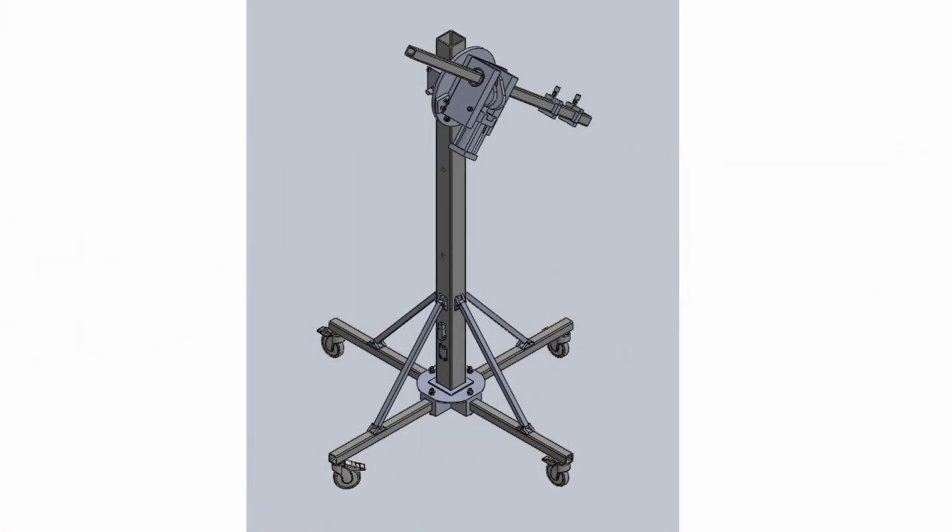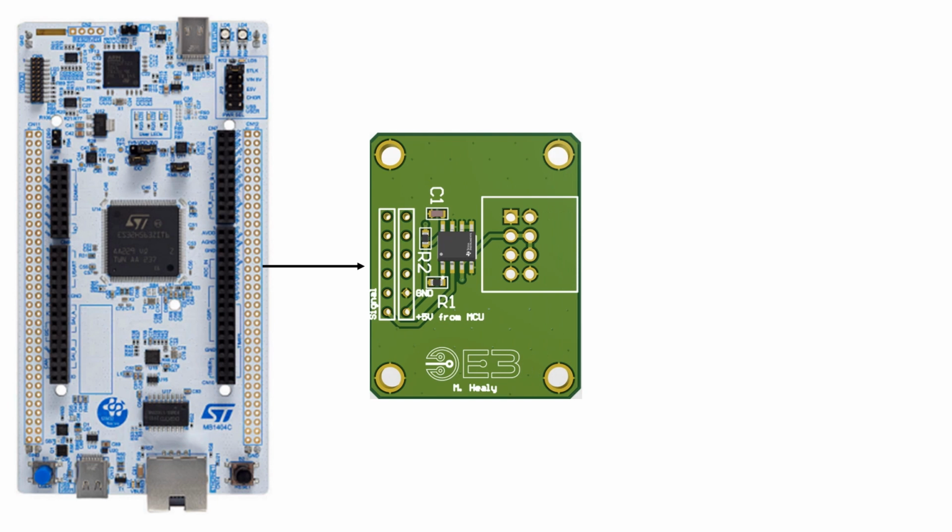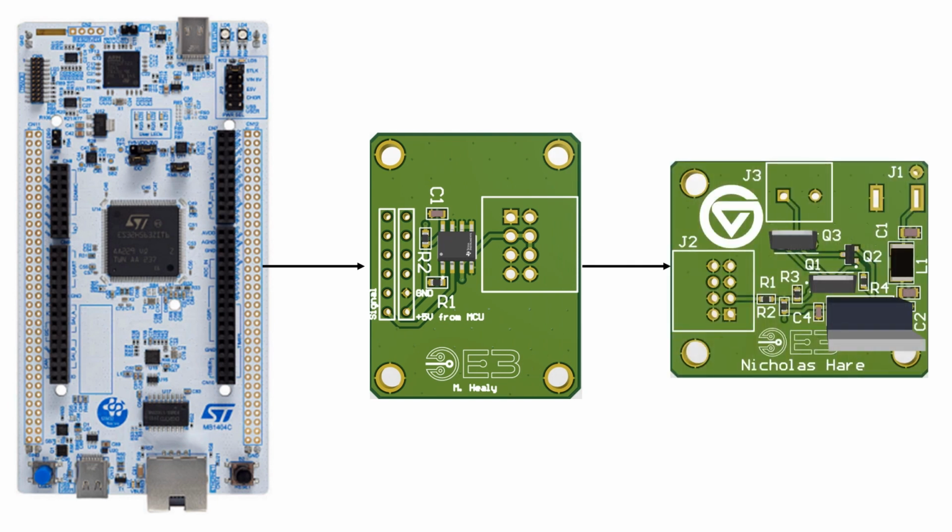The boresight angle is adjusted by pulling a pin from slots which vary between +5 and -40 degrees. The pin should be placed into the respective pinhole to hold the arm in place once a desired angle is reached. In-house software, a low-current microcontroller and fiber optic cable are used to power the pneumatics controller.